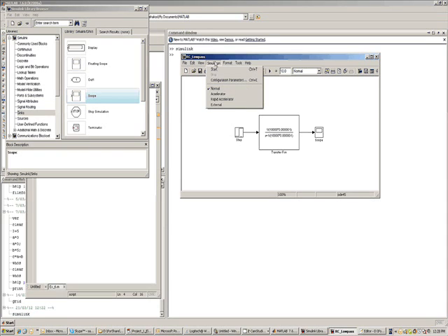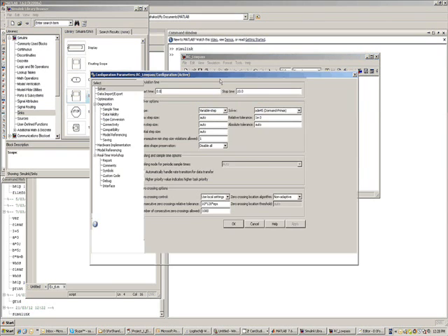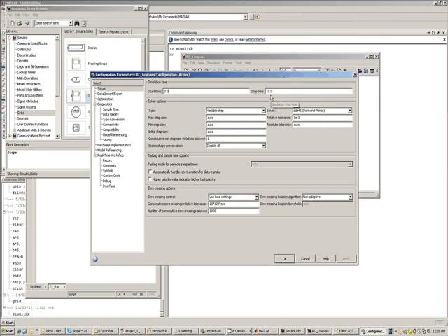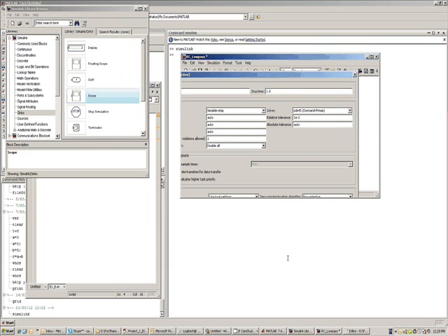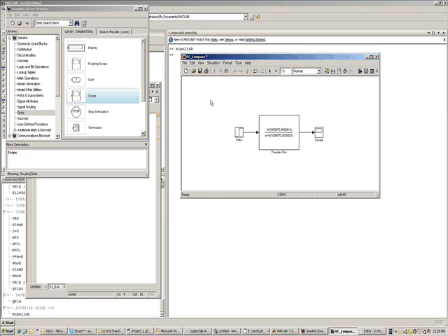Then in the simulation submenu, hang on, we can change the configuration parameters from the pull down menu. So it simulates for 10 seconds. 10 seconds I guess is too many. Let us simulate it for perhaps 1 second and see whether it reaches the steady state.